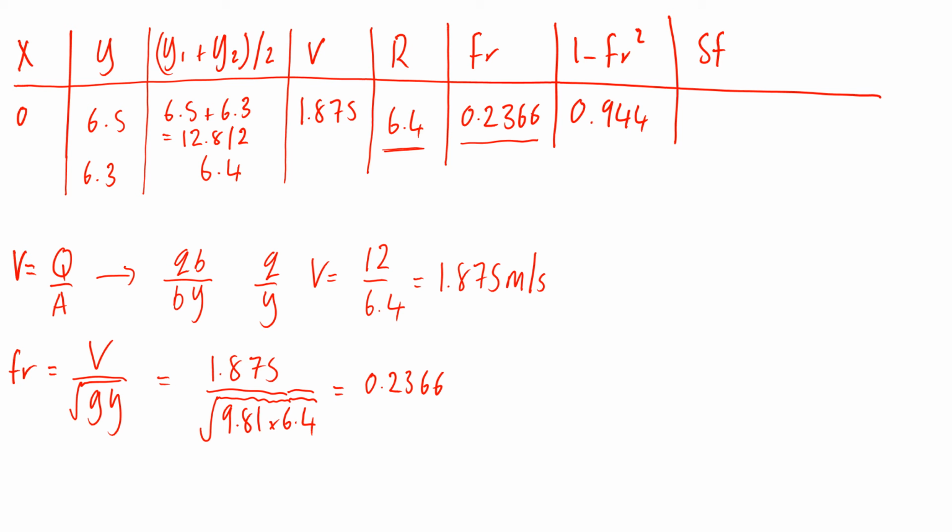So the Chezy equation is Q equals A C square root of R S_f. Now R is equal to y, Q is equal to Q_b, and area is b times y. So if I write all that out again, you get Q_b, which is Q, equal to area, which is b times y, times C times y to the half, and then S_f to the half.